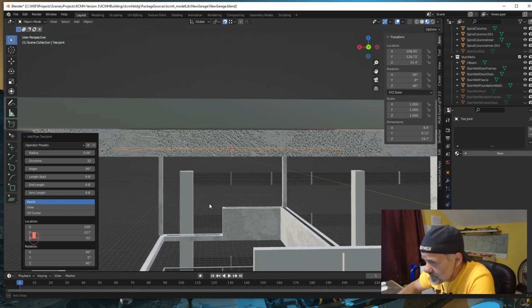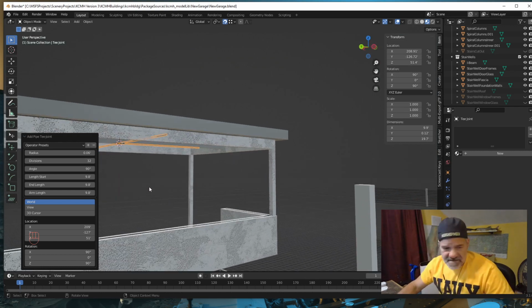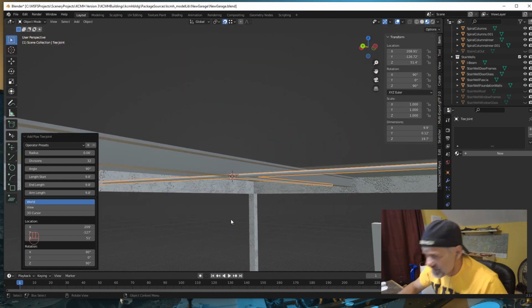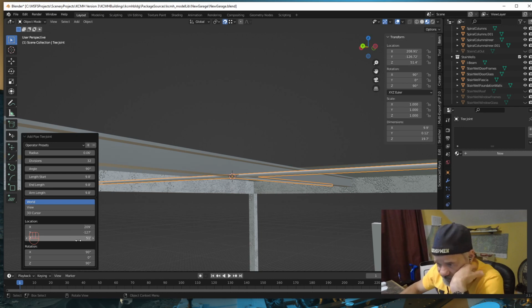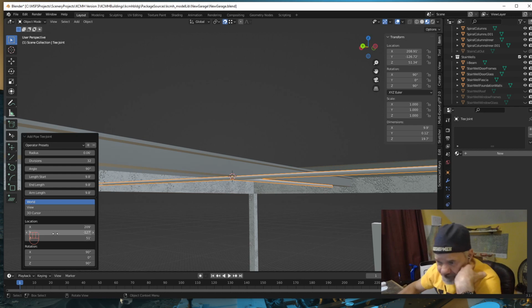All right. But I believe it is inside of our I-beam. Yeah, it's half inside of our I-beam. So let's drop that down 0.06. So Z, here you can just do a minus 0.06. Did you guys see what I did there? You don't actually have to get your calculator and subtract 0.06 from 51. You can just select the 51, put a minus, and then the size, and it will automatically do the math for you.